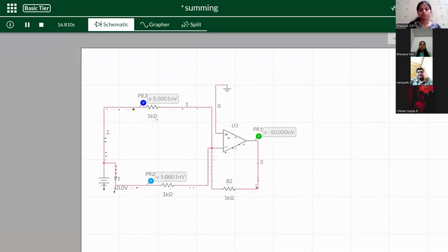Now I am going to state the objectives of this project. To design a differential amplifier using an operational amplifier and same value resistors, ensuring balanced input paths for common mode rejection. To validate the behavior of the differential amplifier by applying identical voltages to both inputs and confirming a zero or near-zero output, illustrating noise suppression capability. To understand the significance of resistor matching and feedback in maintaining amplifier performance and accuracy. To analyze the simulation outcome and verify the observed results align with theoretical expectations of differential amplifier operation.